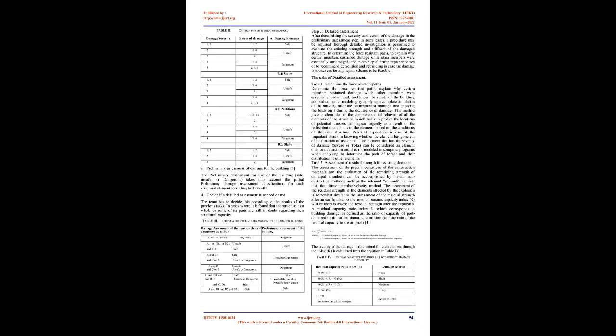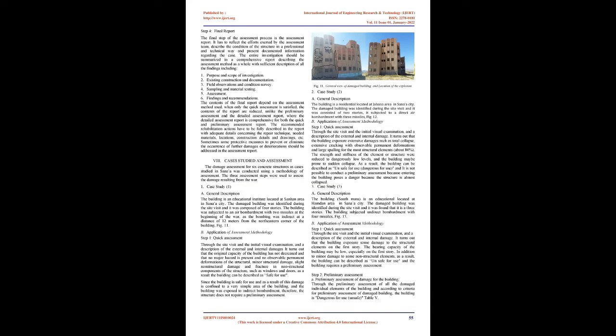After determining the severity and extent of the damage in the preliminary assessment step, in some cases a thorough detailed investigation may be required. It is performed to evaluate the existing strength and stiffness of the damaged structure, to determine the force-resistant paths, to explain why certain members sustained damage while other members were essentially undamaged, and to develop alternate repair schemes or to recommend demolition and rebuilding in case the damage is too severe for any repair scheme to be feasible. The tasks of detailed assessment.